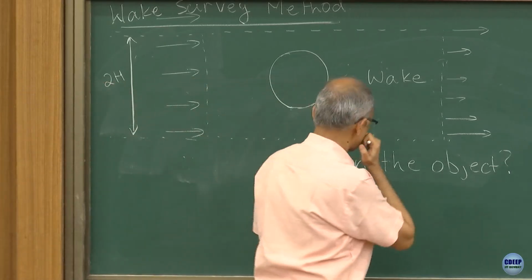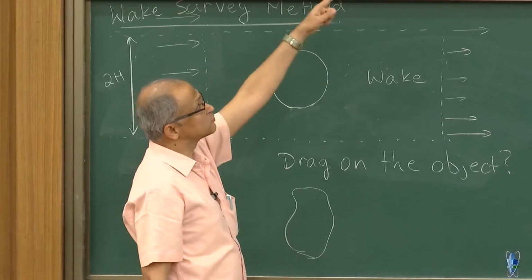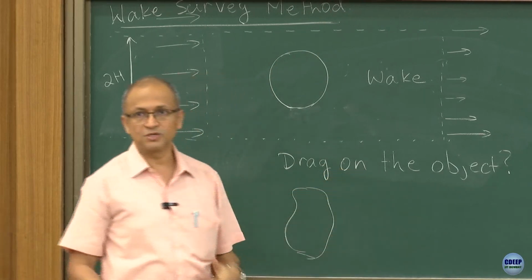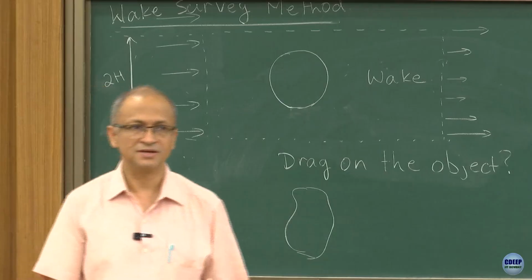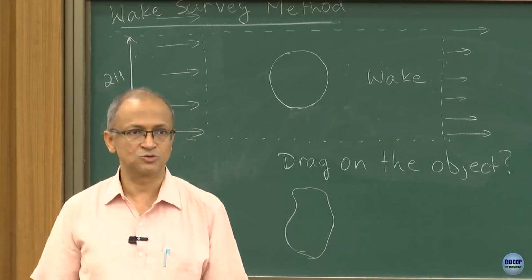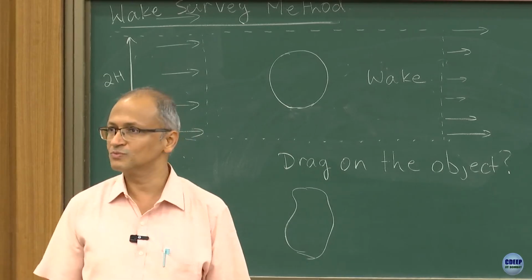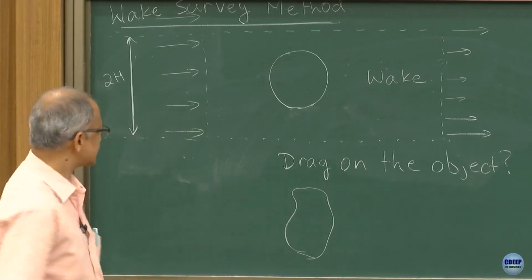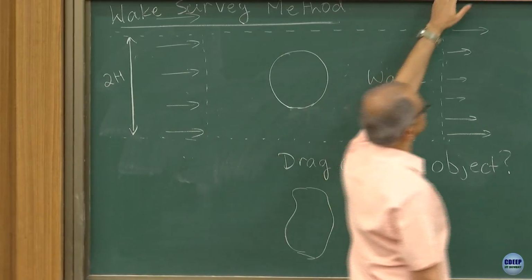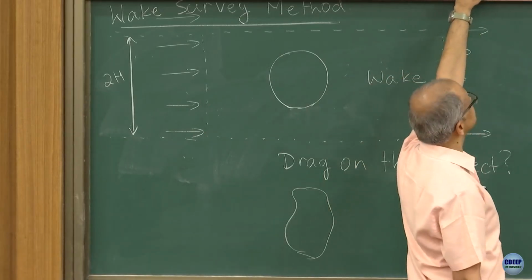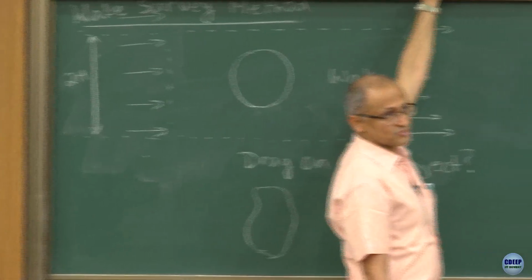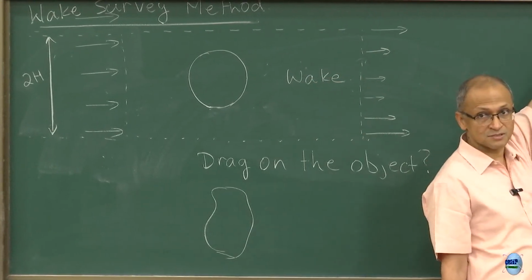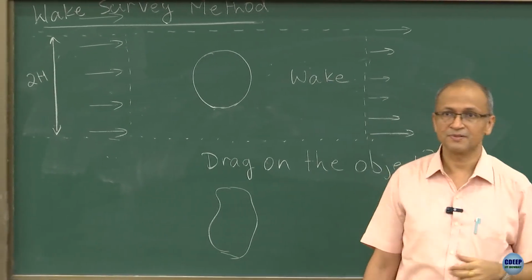Now, we have written down both these equations. When we are talking about drag, it is going to be primarily because of the momentum deficit, or the momentum is just going to be different, and this difference in the momentum will lead to a force, and that force is what we are calling drag. If I look at this equation here, at steady state, this term is not going to be very important for us, or it will go to 0, whereas the last term is what will lead to this force which is going to be acting, correct.